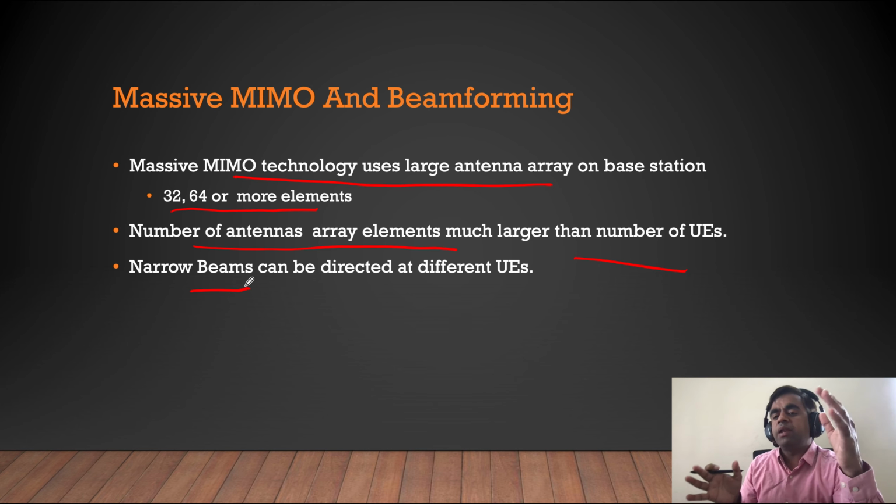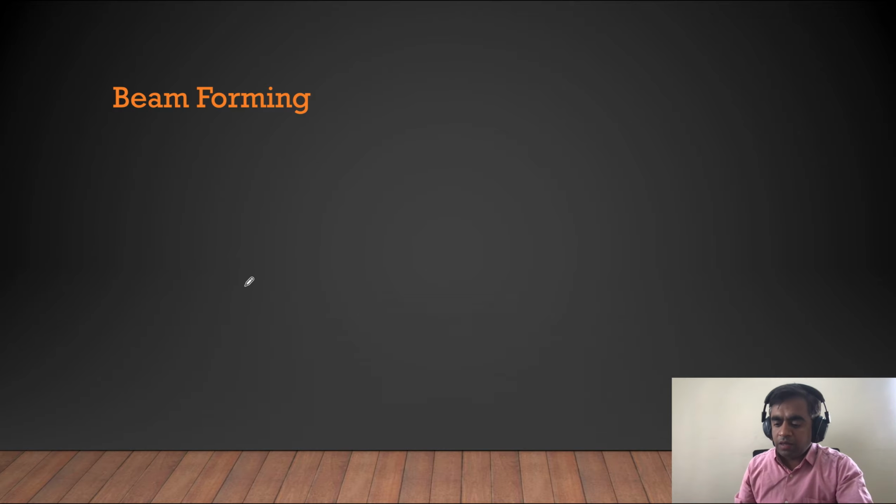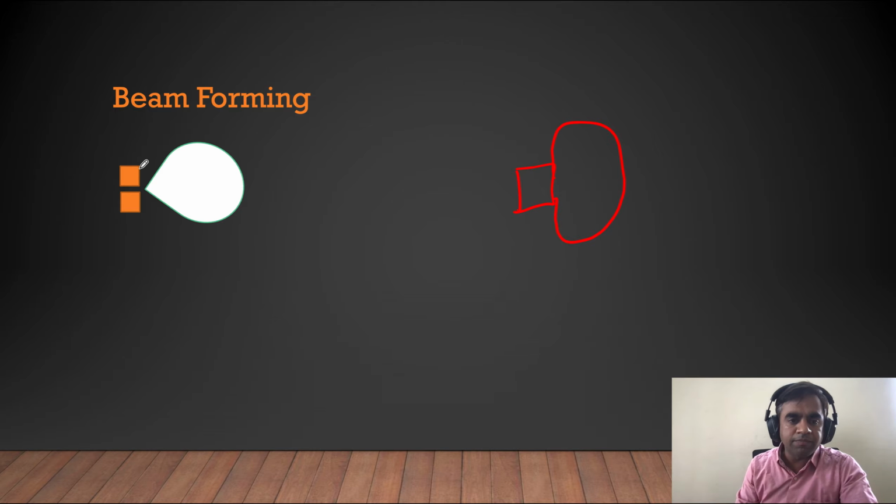When we combine these multiple antennas, is there a change in the signal that is getting transmitted by the transmitter? So let's try to understand the concept of beam forming. Let's say we have this one antenna, which is here. When it transmits the signal, it goes like this. It's like you turn on the light and it scatters in front of you in all the places. But then what was seen is that if we combine more than one antenna here and feed them the same signal, it actually results in a bit more focused beam.